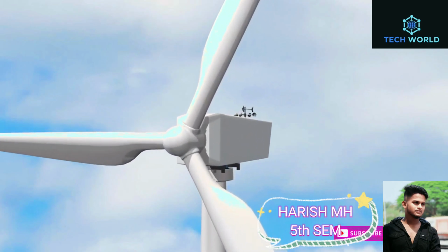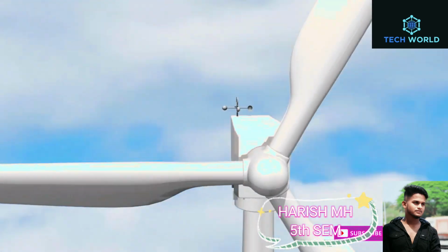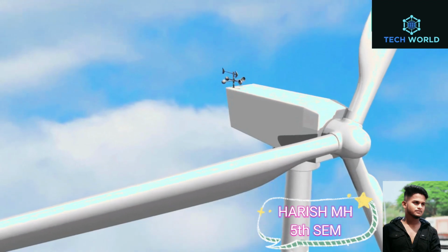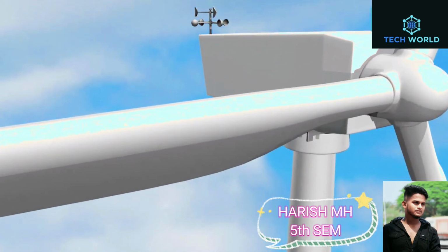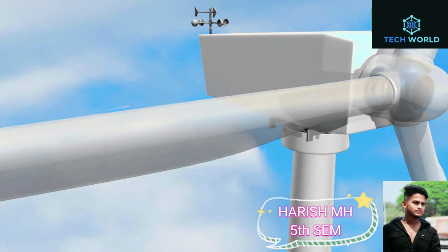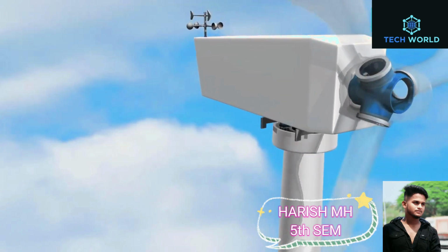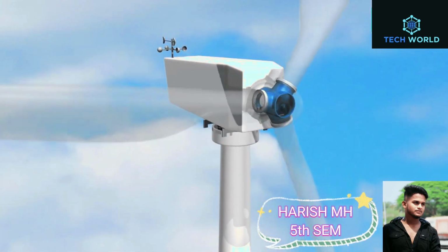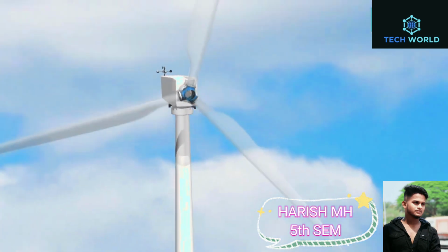The wind runs through the turbine's blades, decreasing the air pressure on one side of the blade. This causes a difference in air pressure between both sides of the blade and generates a force on the blade. The force rotates the rotor, but at a slow rotation speed. The speed of the blade is not linked to the produced electricity. For this reason, a gearbox is connected between the rotor and the generator.